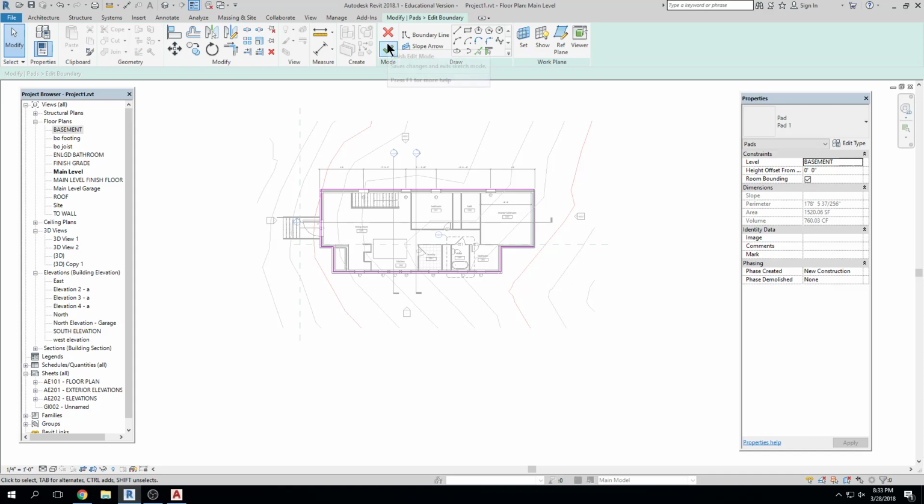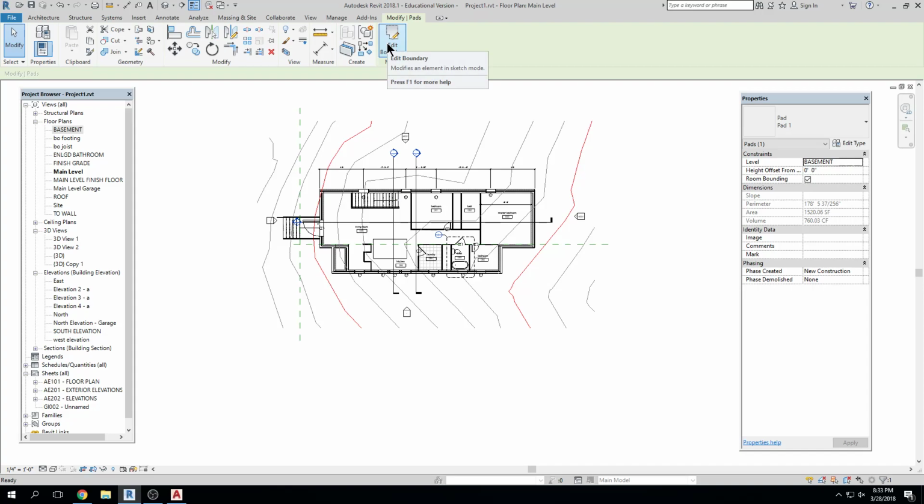So I think that in Revit, basic topography is really easy to generate, right? And it's nice to give a ground plane so that clients, and whoever's looking at it, have a reference for what it's going to look like. For a lot of sites for builders, you have a pretty good chance of getting a flat site, and it's not a big deal. People just want to see how the ground plane is interacting with the house, right? Or even a guess, like it's very level with the road at the front of the property, and it slopes up 3 or 4 feet. It's nice to see, right? And we can generate that to show the design intent.